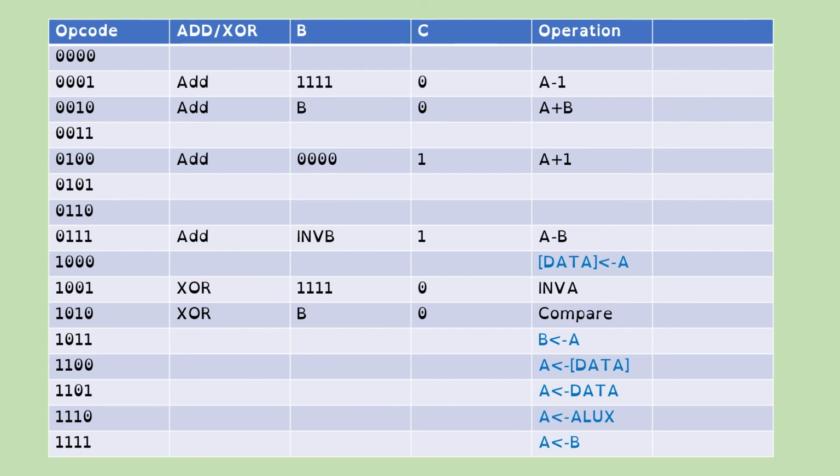And then the contents of, so for the top blue one here, the contents of the A register goes to the memory location that was previously held in data. Okay, so it's a couple of stages to actually make that happen, but there we go. So that is our data transfer, our register transfer operations dealt with. We've done them in the bottom half of the table.